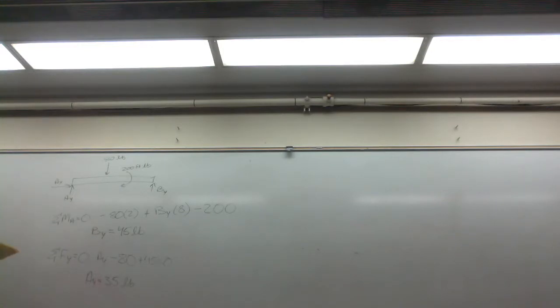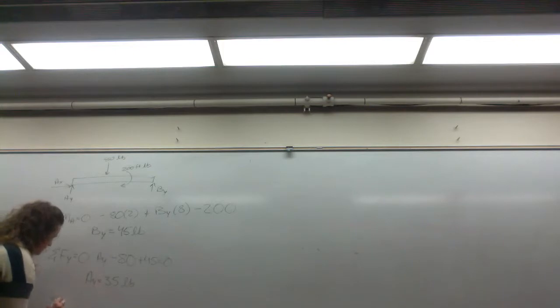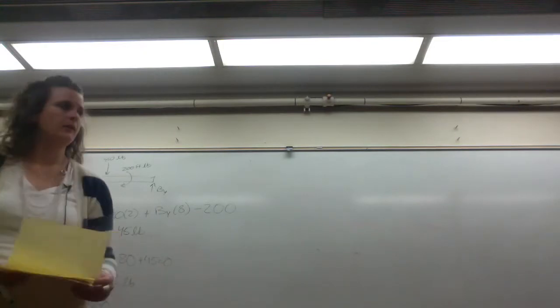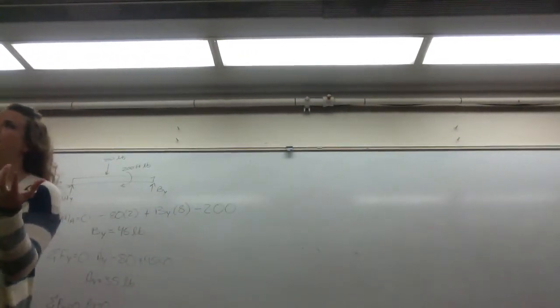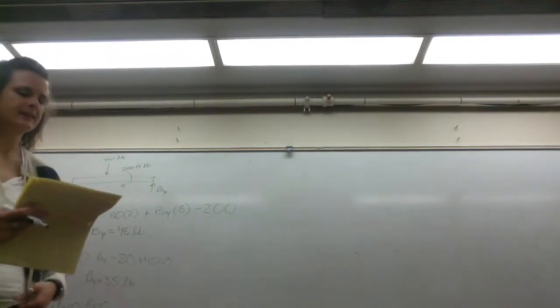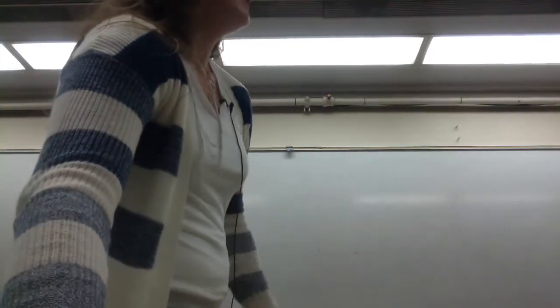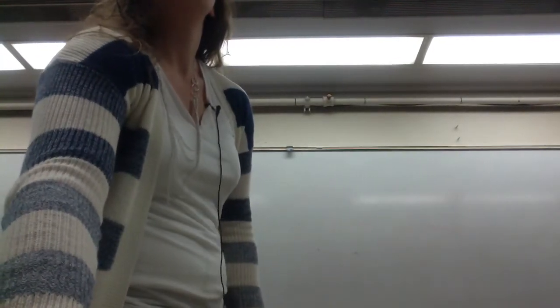So we've solved for our reaction forces. Okay, if we sum the forces in the x, we know that AX is equivalent to 0. Right. So in looking at our steps, we've completed step 1. And now the second step says to section off the beam based on your loading conditions.